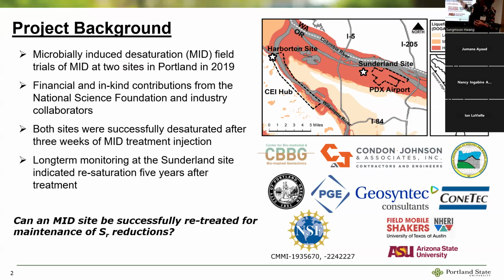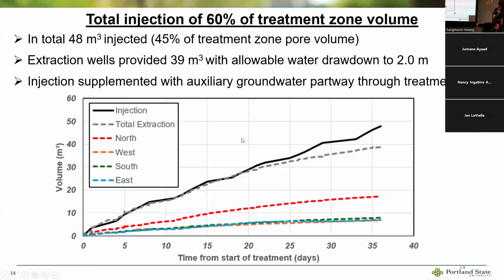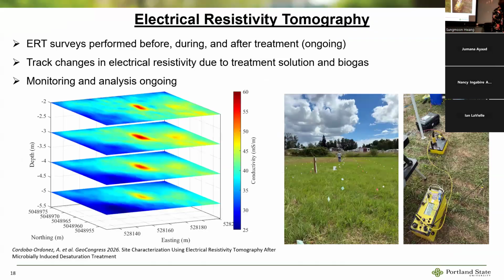But just to the west of the site, right here, there is a levee and a drainage canal as well. So that could also be influencing and maybe pushing. And that actually is something that we've discussed. When you look at these ERT surveys, the drainage canal is here, and we do see that the treatment solution, the substrates, are being pushed out to the east, perpendicular to that drainage canal. So that's possibly where the prevailing gradient is.